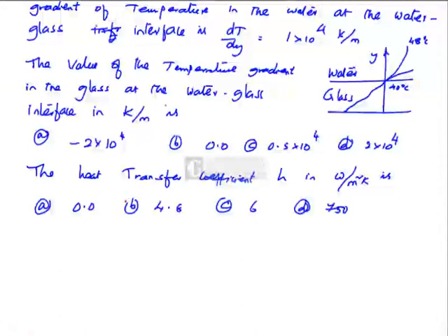Actually, by looking at the values of heat transfer coefficient given here, we could directly put the value of 750 if you are aware of the probable values of convection heat transfer coefficient, particularly when water is the coolant. I had already given the ranges of h earlier. Free convection in gases is 3 to 25. Forced convection in gases is around 100 or 150 watts per meter square Kelvin. But it is a liquid involved here. Water is an excellent coolant. So the expected answer for heat transfer coefficient would be 750. We would also calculate and check this answer.